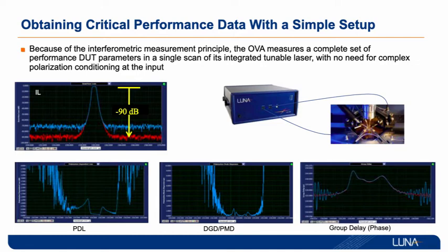And of course, this is also a very fast test, so you can get a lot of testing done in a shorter amount of time. If you're probing even just test device die at the wafer level, you don't want to spend 24 hours testing one wafer. You need to be able to get through it quickly. So we stress that you need to be well under 1 second per test, if not faster than that.